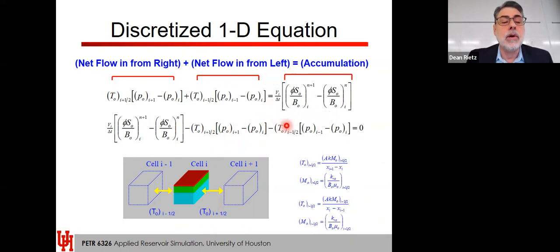And then we have over here our volume. So this is our accumulation term, porosity and our oil saturation, and then B sub O, minus our porosity, oil saturation, B sub O, at N plus 1. So the N plus 1 and N, I believe that's the time step. That's the accumulation term. So this minus this is a different time step. I'd have to check this, or you could check this. This I plus 1 and I minus 1, I think they messed up the nomenclature. This probably is N minus 1 and N plus 1. Oh yeah, because we separated these out.